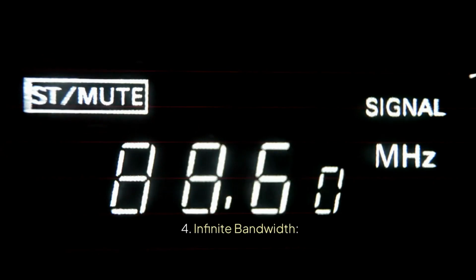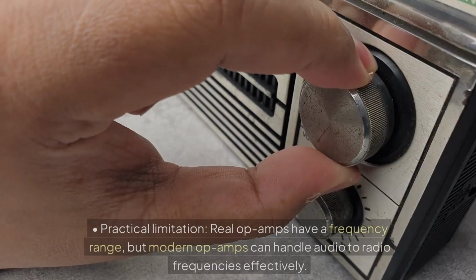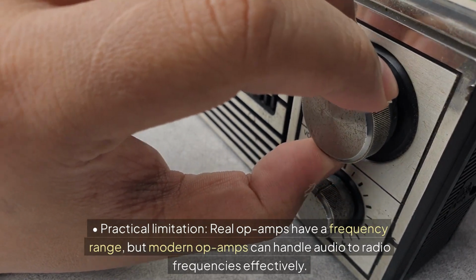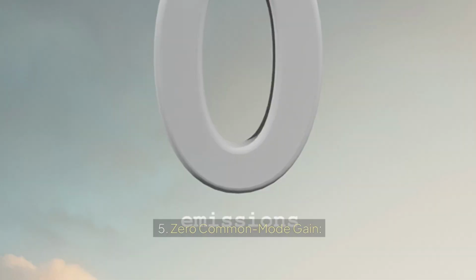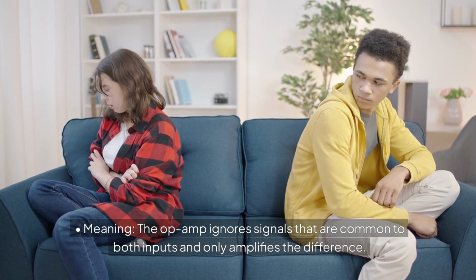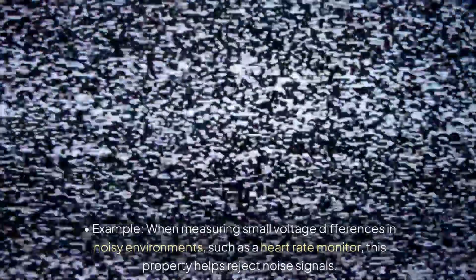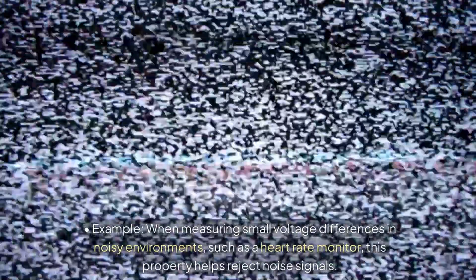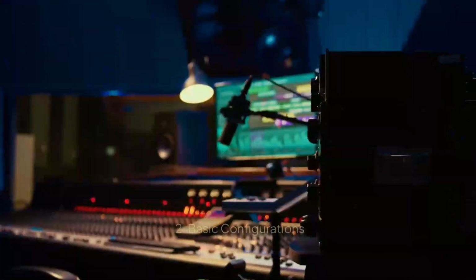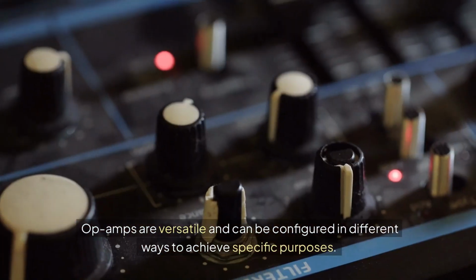4. Infinite bandwidth, meaning the op-amp can amplify signals of any frequency equally. Practical limitation: real op-amps have a frequency range, but modern op-amps can handle audio to radio frequencies effectively. 5. Zero common mode gain, meaning the op-amp ignores signals that are common to both inputs and only amplifies the difference. Example: when measuring small voltage differences in noisy environments, such as a heart rate monitor, this property helps reject noise signals.